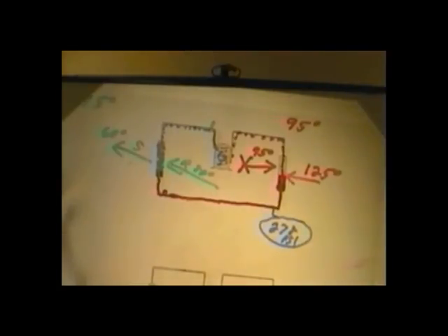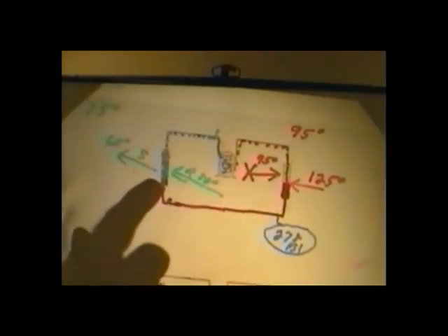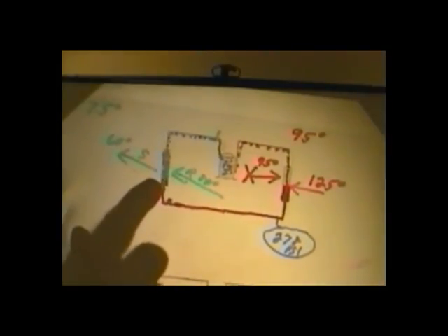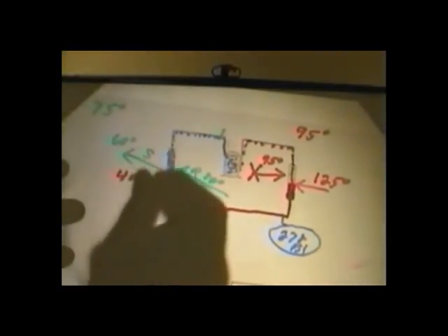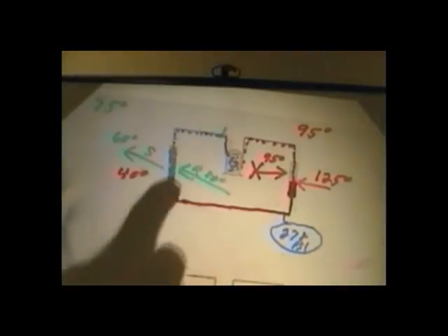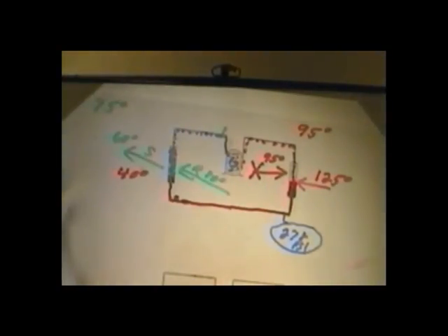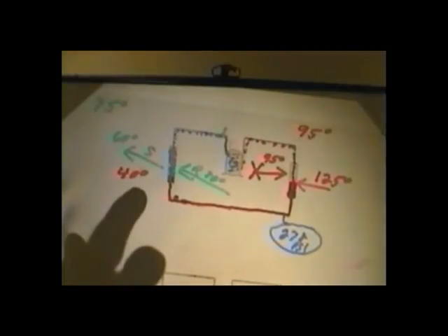Do you happen to know typically about what temperature that evaporator would be in order to get a 20 degree differential? Now you may know and you may not. It's actually about 40 degrees, correct, right. So Ray was just going to say that, but I beat him to it because I wanted him to have the right answer. If we're saying that we have a 40 degree evaporator, that means the entire evaporator is full of liquid refrigerant, changing state, and we got 40 degrees.